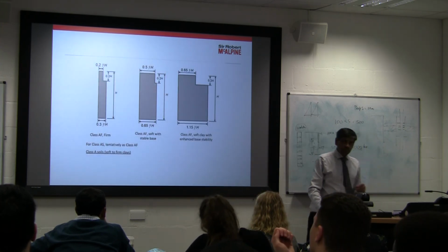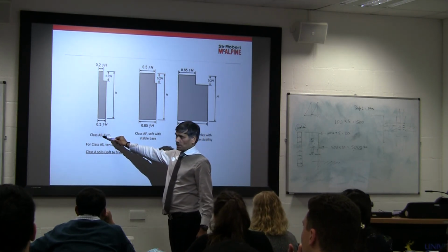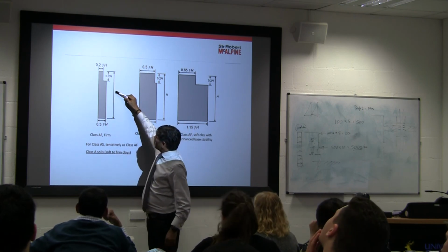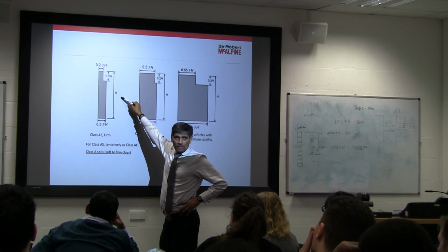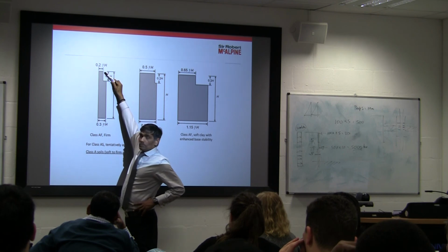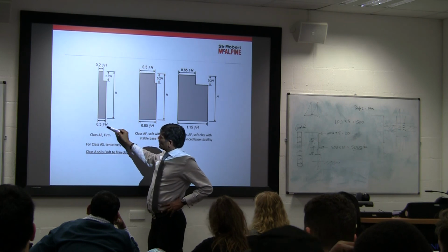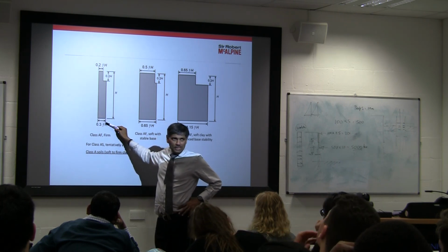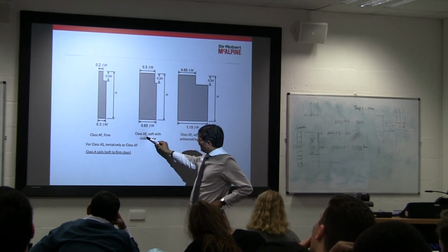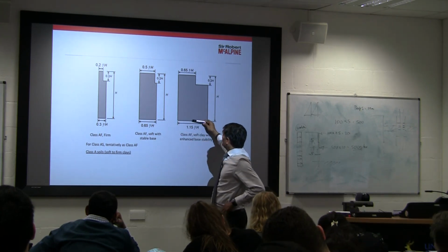Once you classify them, then this is the approximate pressure distribution. So A is for a very stiff wall, and B is a soft wall. So you can see here the pressure distribution. If that is the height of the dig, 20 meters, 30 meters, 10 meters, that's the depth of the basement. Because you are very close to the ground, you get a bit less pressure. As you go deep, you get what is called a plateau, a steady state condition of 0.3 gamma H. If it is a soft wall with a stable base, again type A, then you can see a different distribution. Soft clay with enhanced base stability, you get a different distribution.